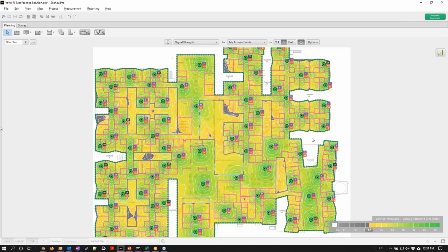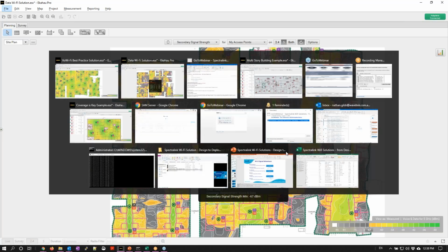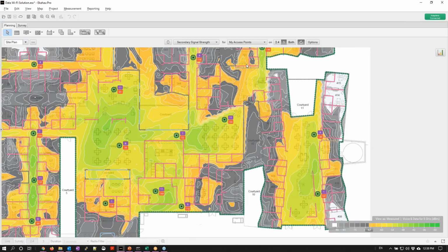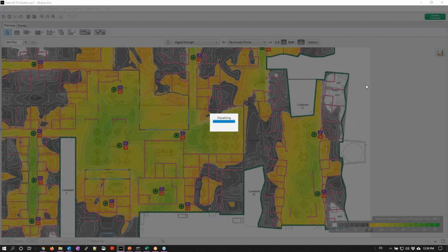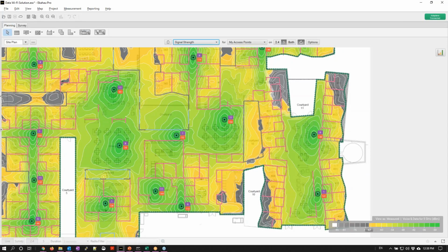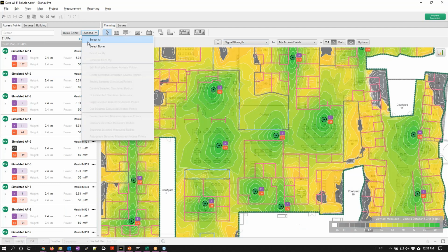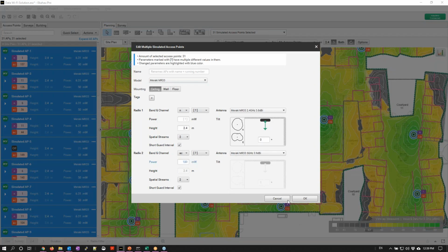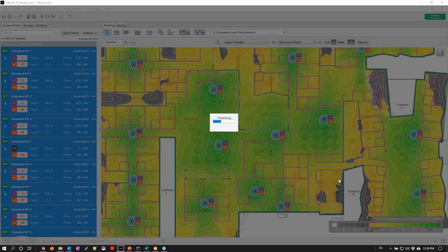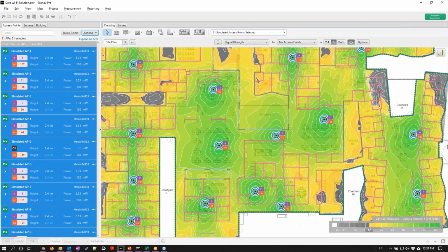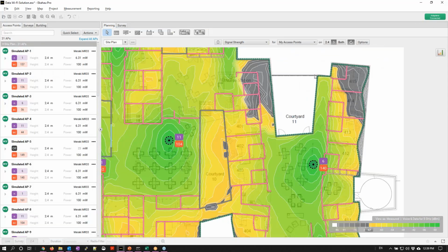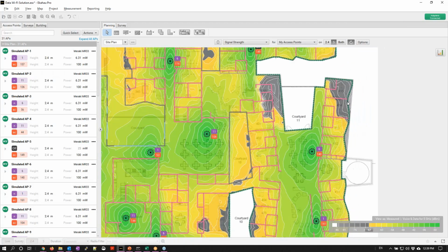So one of the areas which is a great example is this area down here, where there were only 2 access points scoped, where none of those rooms have secondary signal coverage, and not even primary rate coverage. Again, you can go to the level of what I like to call fudging the figures and go, oh, we'll just turn the power up on the APs. But again, you're just stressing the access points out, and even that hasn't actually fixed it. It's at 100 milliwatt, so that's fairly high in its power output. It's still not facilitating coverage in those areas and in those rooms.